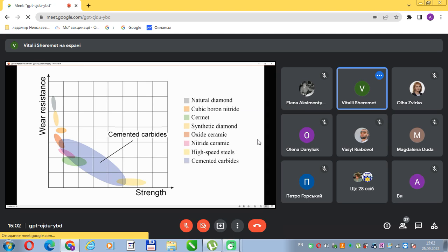The principle of the action of grain growth inhibitors is well known, I think. Coating an interlayer on tungsten carbide particles, making it difficult for elements to precipitate from the liquid eutectic on the surface during crystallization, during cooling. But what about cold isostatic pressing?